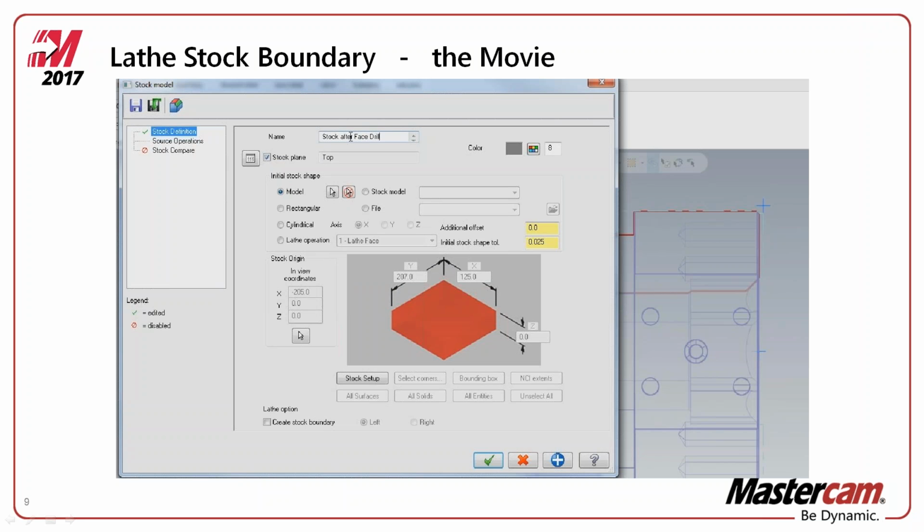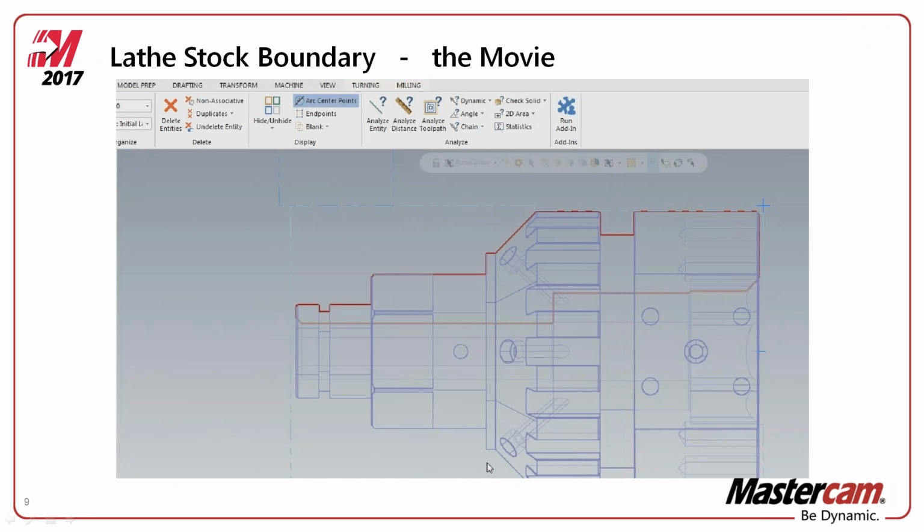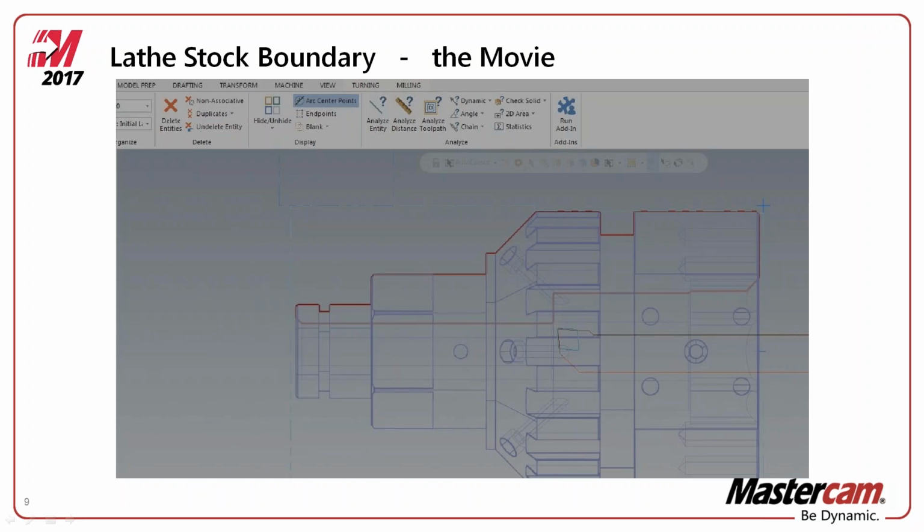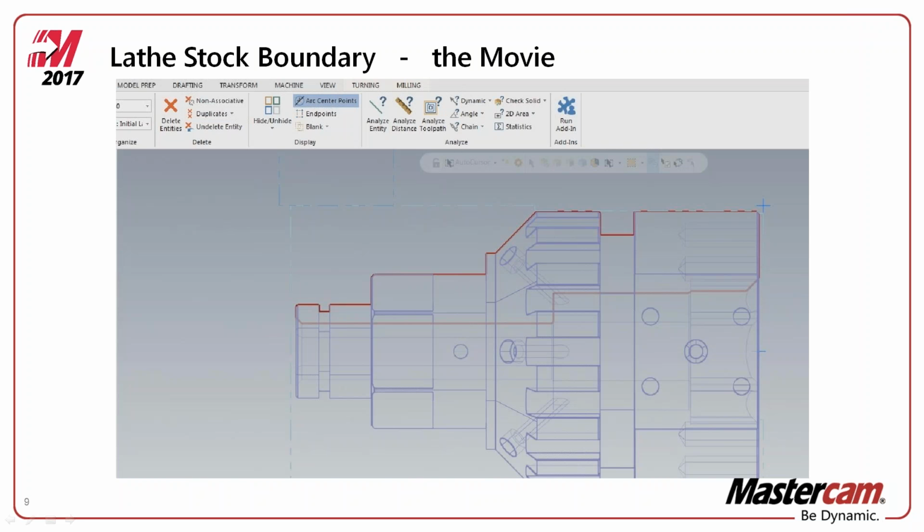Of course, I know that I went in there before with a drill and basically cleared everything out, so what we can do is create a stock model inside of the lathe. We can reference what our initial stock is going to look like off of a particular toolpath. We can create a boundary off of that, and that way when we create our toolpath, it is going to reference that boundary and compensate properly, and you can see it's not going to be overcutting any extra air motion there. So now we're trimming it exactly where I had that drill go in there.